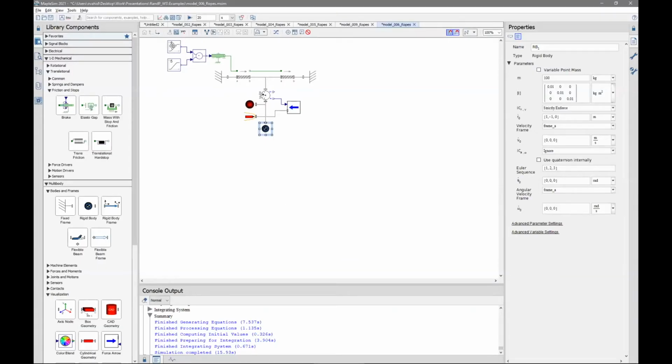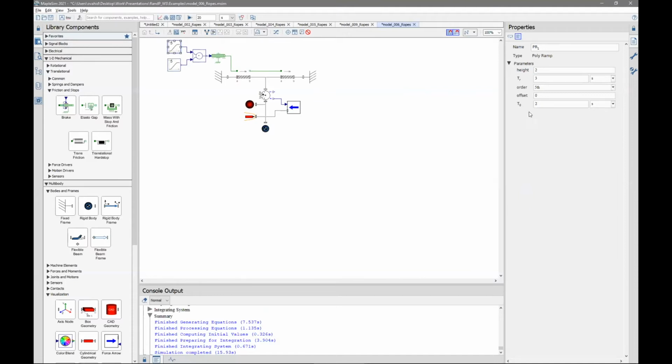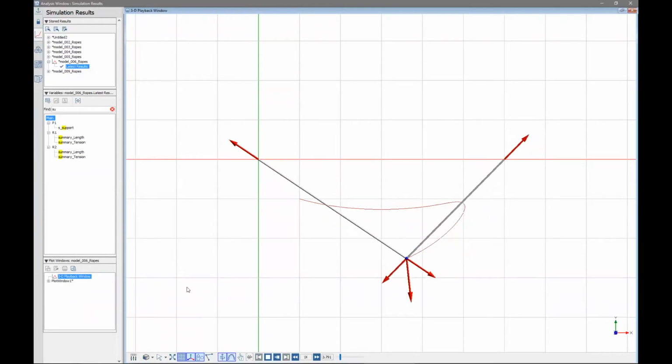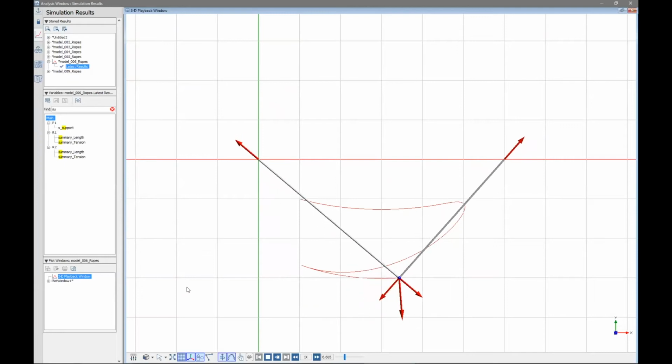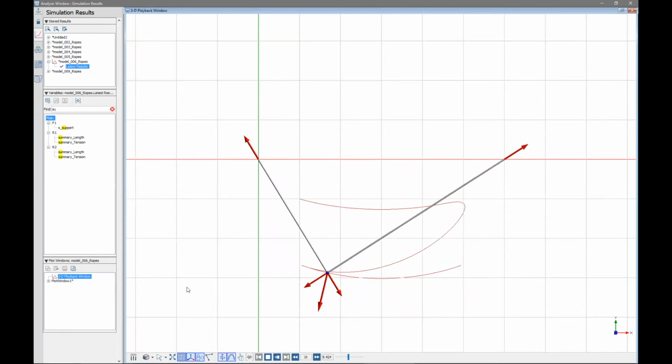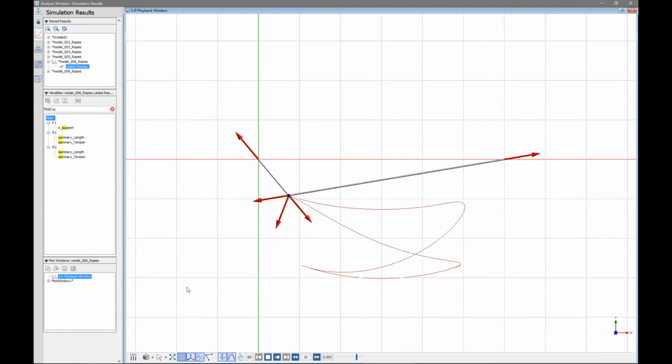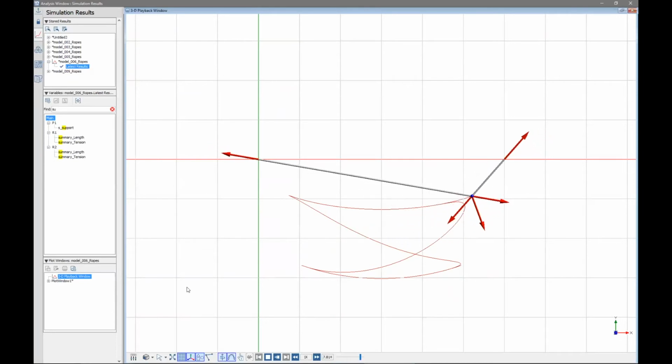Before running it, let's look at the signal that we have. So at 2 seconds, we are increasing over a time of 3 seconds, 2 meters. So we're adding 2 meters to this multi-rope segment as a model. And then at 12 seconds, we are removing that 2 meters that we added. So we go back to where we were. So let's run this. 1 second, we'll just keep everything constant. So the lengths increase, and this will just sit there and slide without any more changes. And then at 12, we'll come back to our original length and follow the same path as we were originally following.